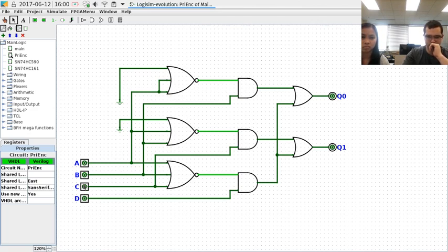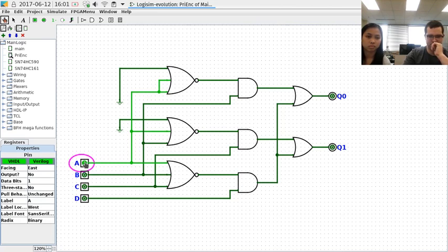These are not inputs from the switch, they're inputs from our digital circuit, but each one corresponds to a switch state. So what we have here, like this A, if it's high, it will be tied to ground at the switch. That means that any of the inputs after it will not override it.